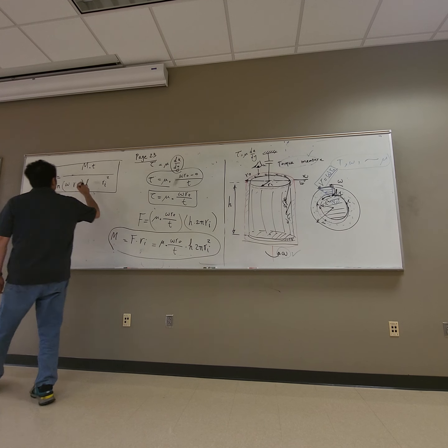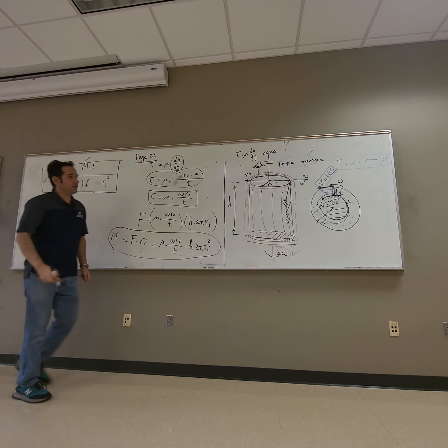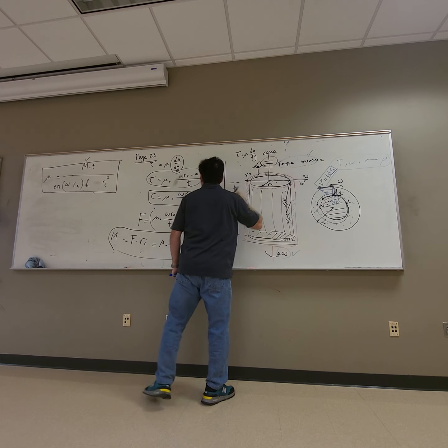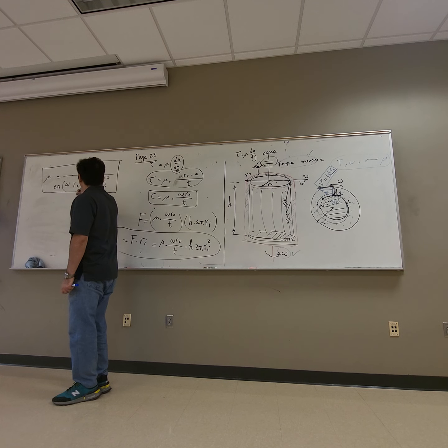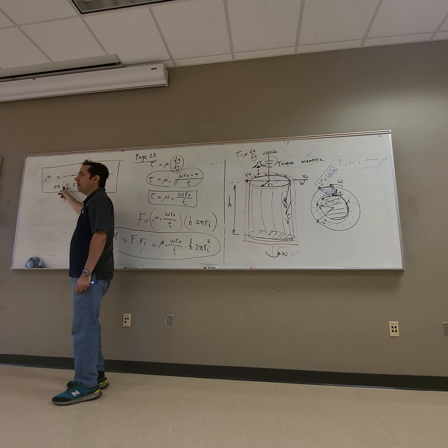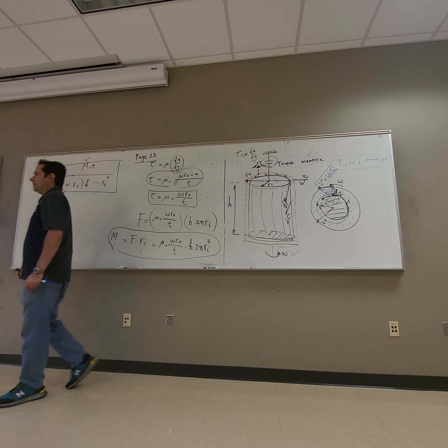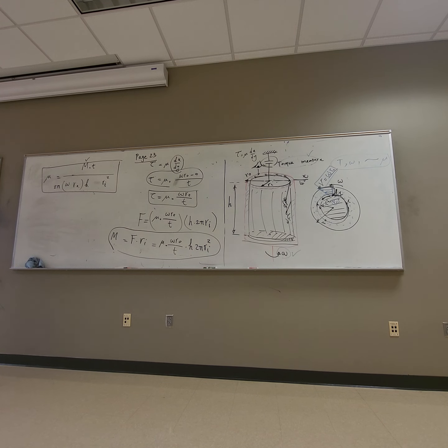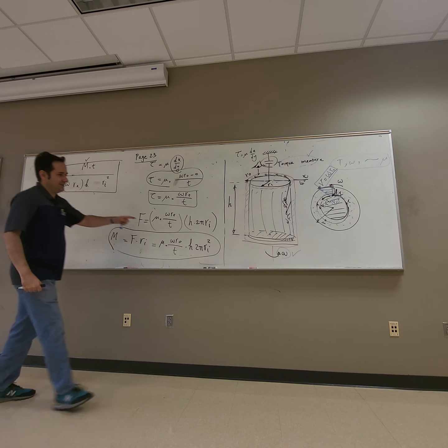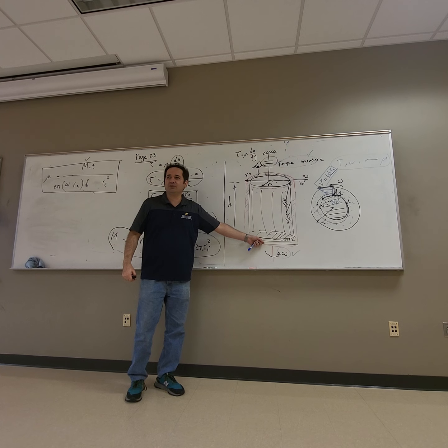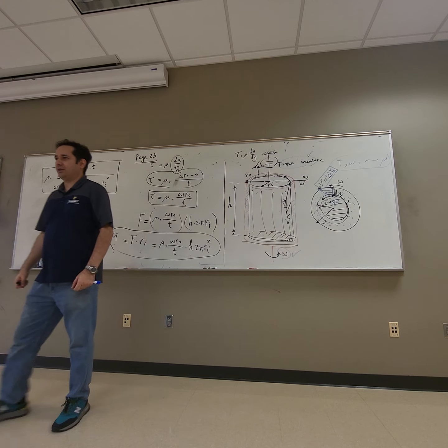Now, if I measure torque, how do you measure torque? This sensor right here. You measure torque, you have thickness, all the dimensions, you have the omega, and then you get fluid viscosity. If the torque is just too much, what do you do? You reduce the velocity, right? Otherwise, your machine will break down, okay?